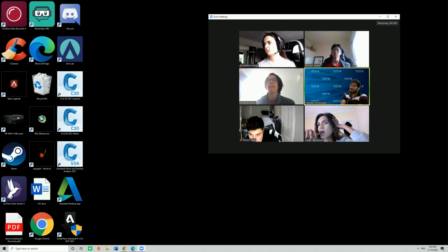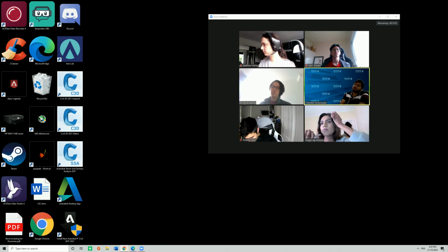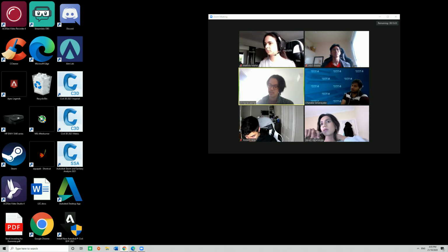Then serviceability always will be satisfied. Then in this problem also, if you are finding the final settlement, the pile diameter is 1 meter, no? That means your answer should be less than 10 millimeter altogether. You'll get less than 10 millimeter definitely if you are using that method. Okay, got it.